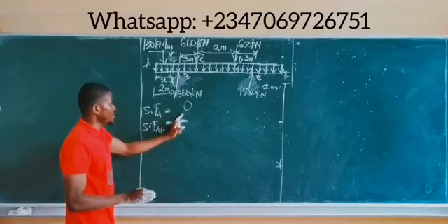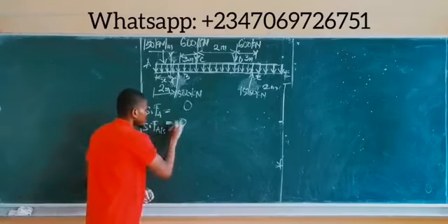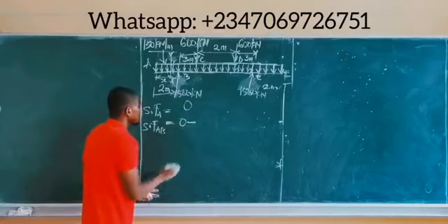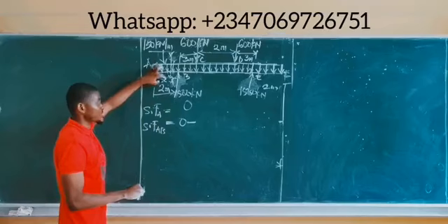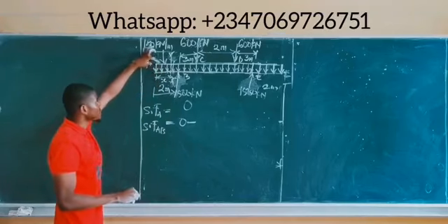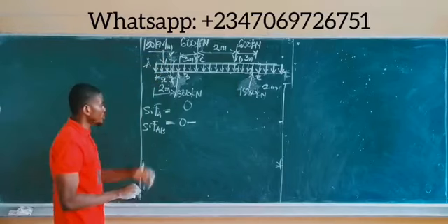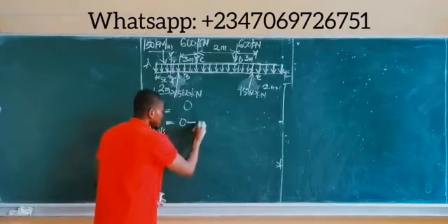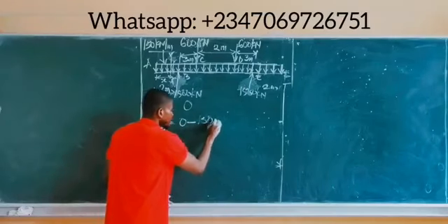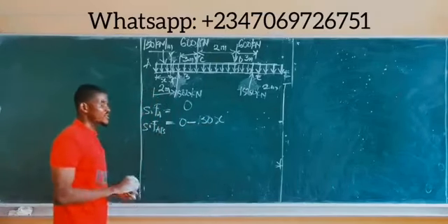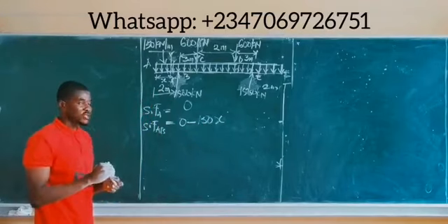And that's simply equal to, okay, the last shear force we had is the 0, so bring out 0, minus the length of the UDL about the point of section, which is x meters. So therefore, to convert this portion of the UDL about the point of section to a point load, we simply multiply the load intensity, which is 150, by x. X is now the length of the UDL about the point of section.